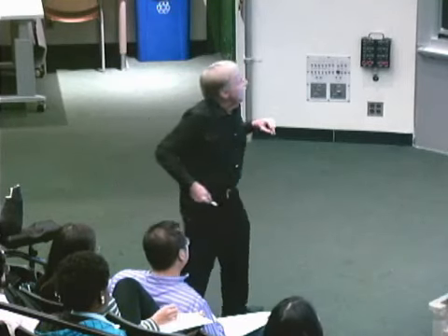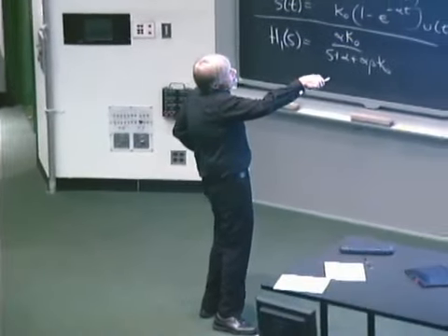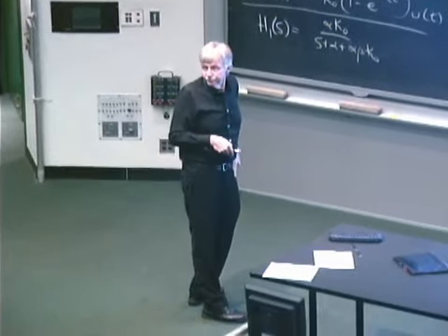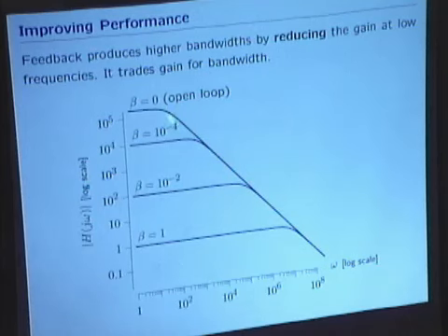Okay? And what you can see is the DC gain is 2 times 10 to the 5th. And there's an AC gain defined by the cutoff frequency. If you compare this expression and that expression, the interesting thing that happens is that the DC response depends critically on beta, but the high frequency asymptote doesn't depend on beta at all. The high frequency asymptote of this is alpha K naught over s.